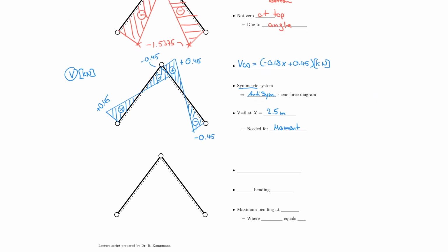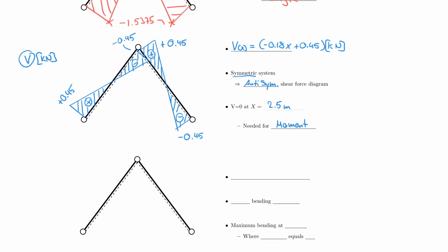So with that said, I can move on to my moment diagram. Just as before and as always, I can bring down my maximum/minimum values, or where my values will be maximum or minimum. And so I have that intersection there and this intersection. My moment diagram will be fairly simple to draw now because I know it's 0, I know it's 0, I know it's 0.